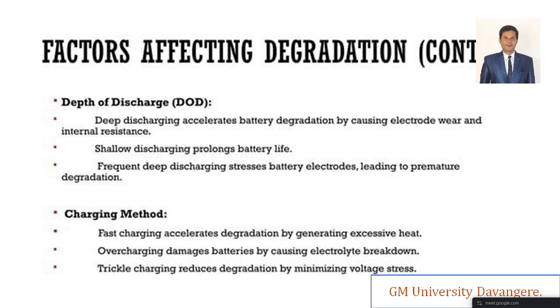So that is the reason we expect to have more charge. That is the only thing we have to understand about battery conditions, right? Everyone has to understand the battery conditions. The depth of discharge: if we charge to 100%, try to discharge to 100% only. At least if it is 20% discharge, that will give the shallow discharge. It will give prolonged battery life also. At least after it comes to 10% or 50%, please go for charging.